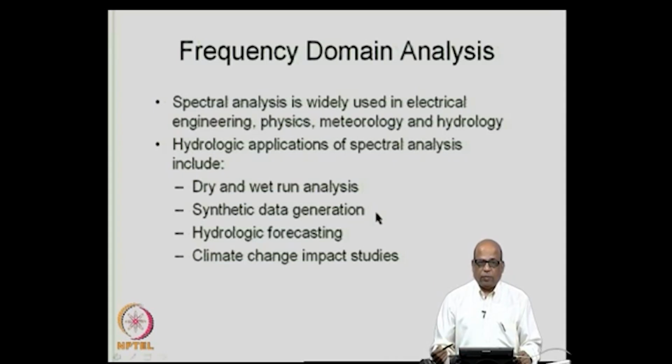We also use it for developing models for synthetic generation, in which we would be incorporating into the models the periodicities inherent in the data, and for that, identification of periodicities becomes important. Even in hydrologic forecasting models, when we are talking about medium term forecasts, let us say over the next season, 6 months, 1 year or 3 years, we need to incorporate the periodicities in the process into the models, and that is where we use the spectral analysis.